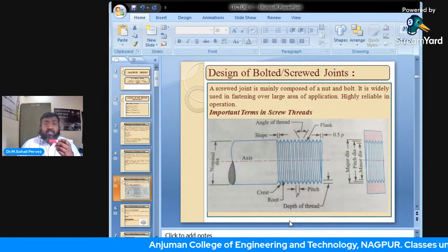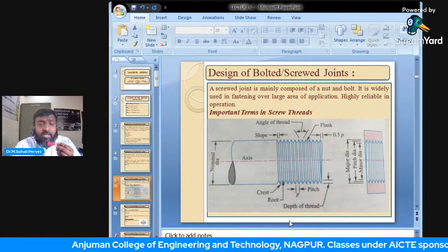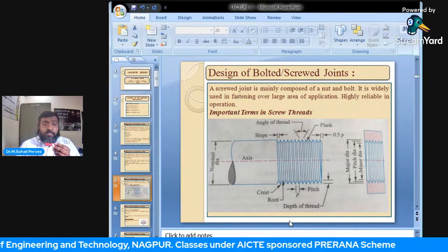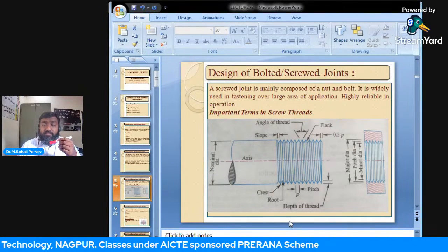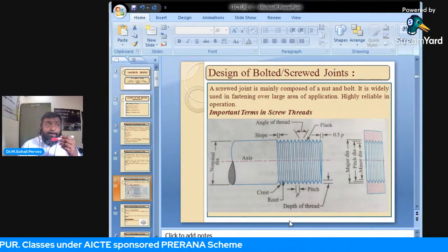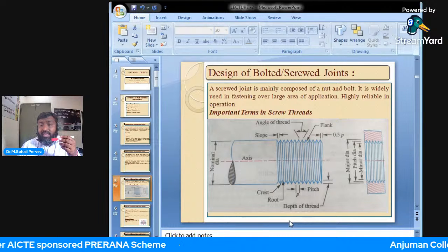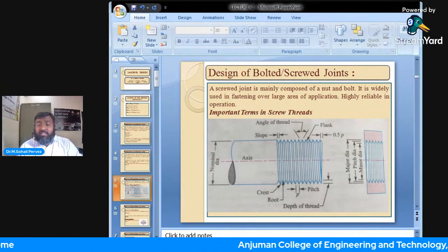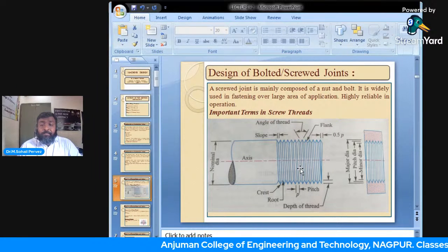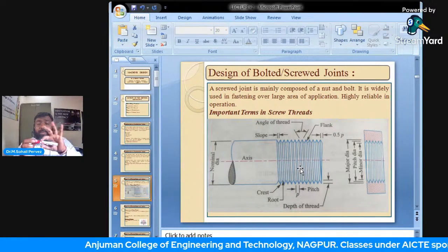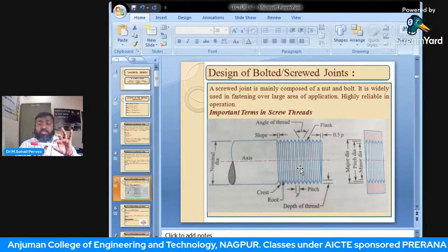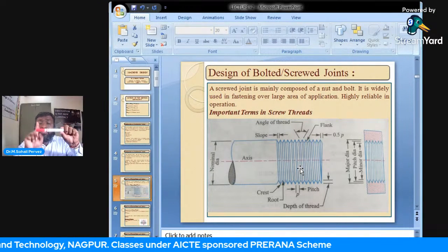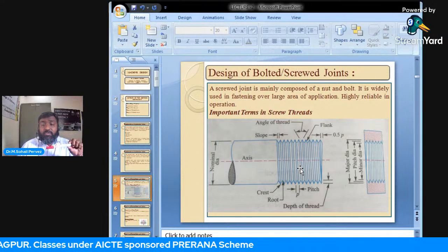Next, we will put this on a lathe machine and we will thread it with some V tool having included angle as 60 degrees. Then in that case, the metal will be removed in this fashion. So this plain portion will be known as the shank portion, and this portion, in our video the red portion, is known as the threaded portion.